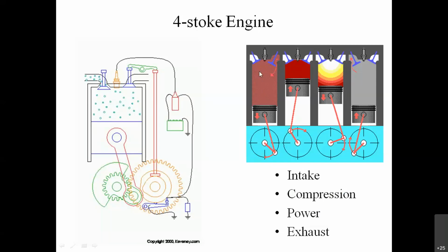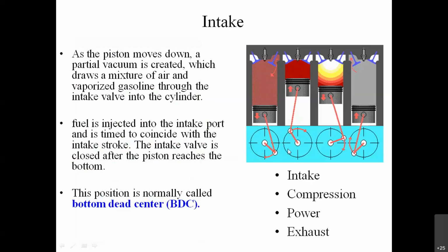Intake usually starts from the top dead center, which is near the spark plug and the inlet and outlet valves. As the piston moves down, a vacuum is created within the cylinder, and that vacuum draws the air-fuel mixture into the cylinder.